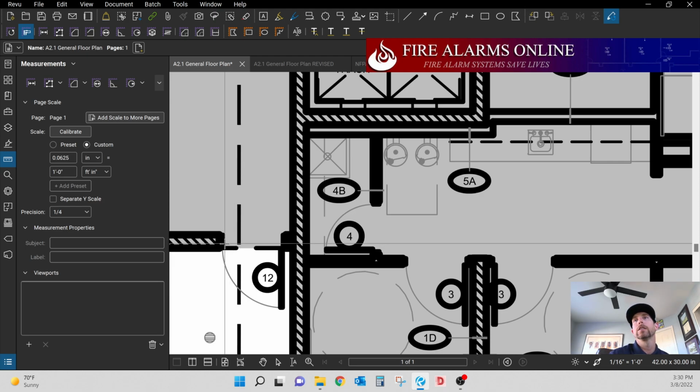From here, select 2 points of reference to measure across. So we're going to measure across the width of this door. So I'm going to select right here. If you hold shift, if you notice in Bluebeam, as you go across, it's kind of hard to keep a straight line, right? But if you hold shift in Bluebeam, it automatically locks your lines in horizontally, vertically, and at a 45-degree angle. So it makes it really easy to just drag across and get a perfectly straight